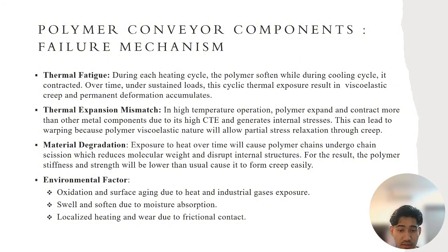Now, first of all, thermal fatigue. During each heating cycle the polymer softens, while during cooling cycles it contracts. Under sustained loads, this cyclic thermal exposure results in viscoelastic creep and permanent deformation accumulates. Thermal expansion mismatch: in high temperature operation, the polymer expands and contracts more than other metal components due to its high CTE and generates internal stresses. This can lead to warping because the polymer's viscoelastic nature allows partial stress relaxation through creep.